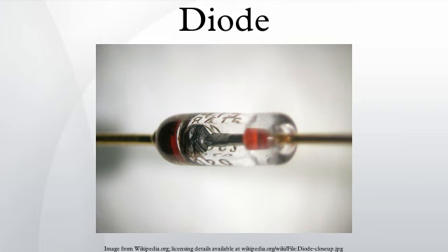Gold-doped diodes. As a dopant, gold acts as recombination centers, which helps a fast recombination of minority carriers. This allows the diode to operate at signal frequencies, at the expense of a higher forward voltage drop. Gold-doped diodes are faster than other PN diodes. They also have less reverse current leakage than Schottky diodes.